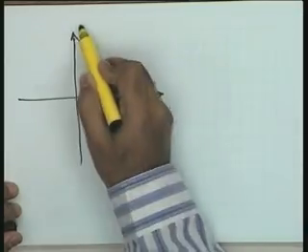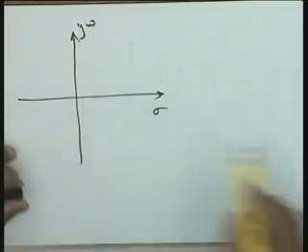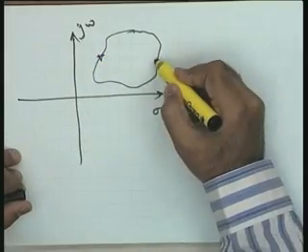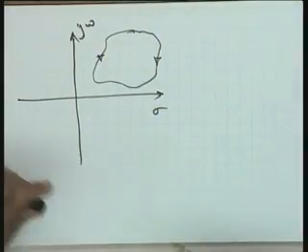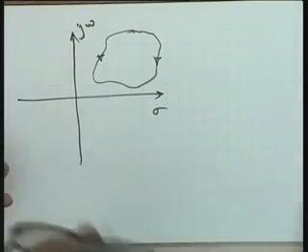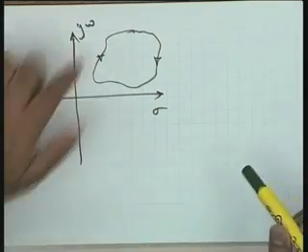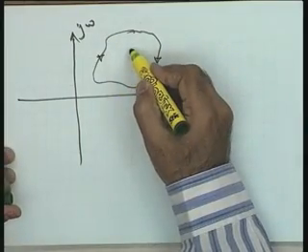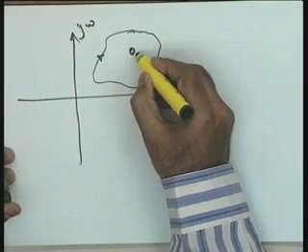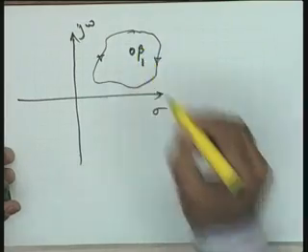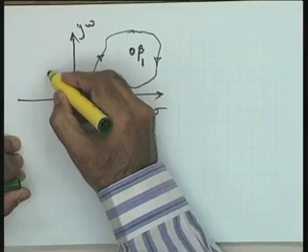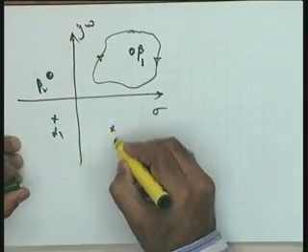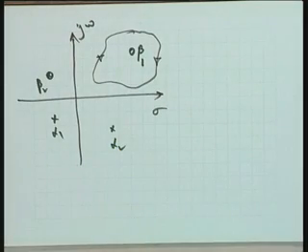The answer to this question will convince me whether my point is well understood or not. I take just a tentative contour in the S plane and let me traverse this contour in the clockwise direction. Help me: what will happen in the W plane, or the 1 plus GS HS plane? This is the contour, any tentative contour I have taken. The only thing I do is this: one of the zeros, at S equal to beta 1, I enclose in this contour. All other zeros, let us say beta 2, and pole alpha 1, another pole alpha 2, are outside this contour. See my point please.